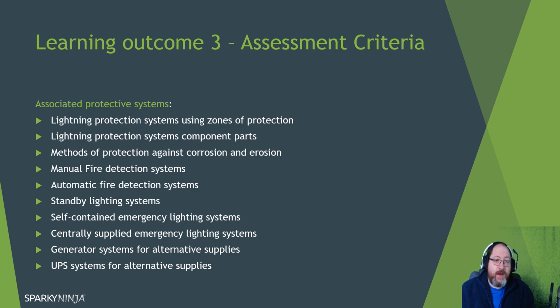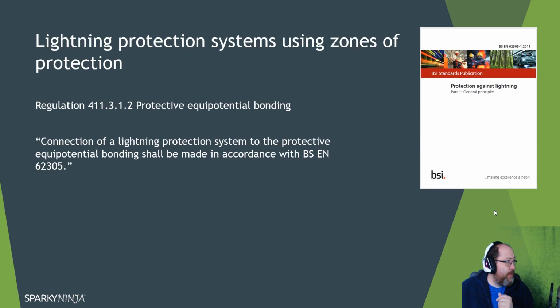If the client is going to put people at work in a building, there are legislative requirements to have a safe work environment, and they'll be pushing other standards beyond BS 7671, such as BS 5266, which gives requirements of light levels for escape and fire, etc. Then you have to think about other supplies. You may have an alternative supply, such as photovoltaic. You may have a UPS system, and there may be segregation requirements between those. So, just to highlight a couple.